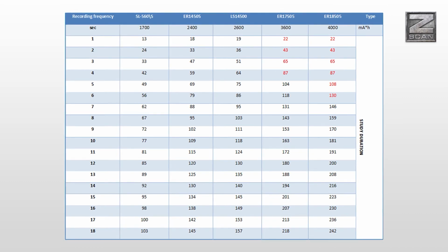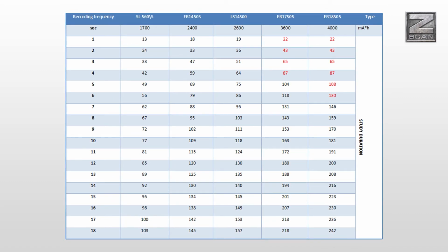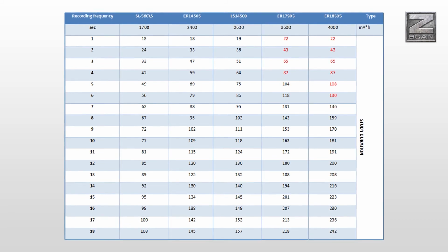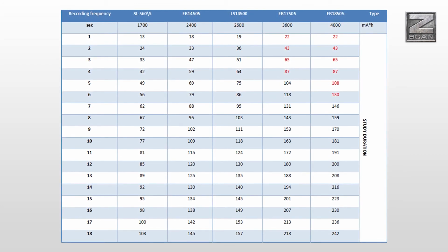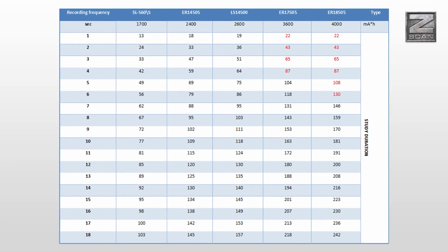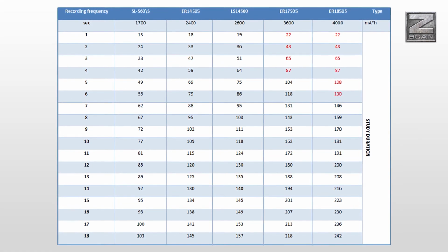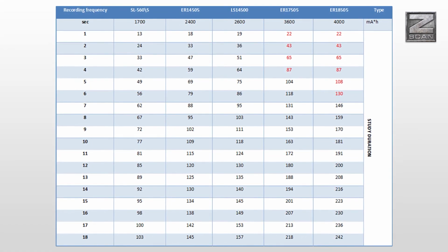for room temperature. It is important to note that the actual capacity of the battery depends on the operating temperature, storage conditions, the passivation parameters, and the data of the manufacturer of the given battery, which could differ from what is specified. For guaranteed operation of the gauge, timely replacement of the batteries is required. A specific battery model should be chosen considering the temperature in the well and the program of the survey.